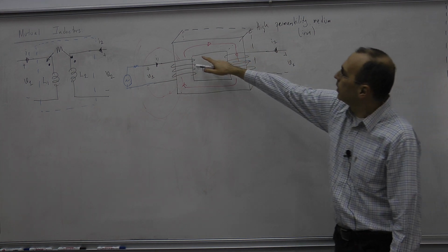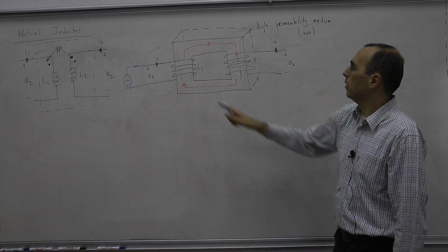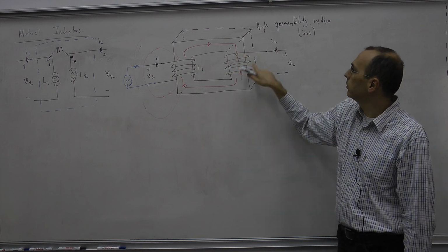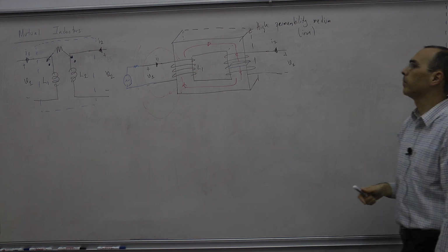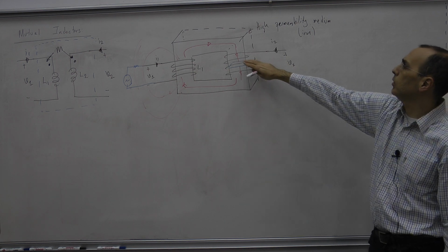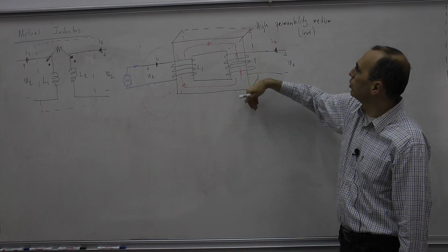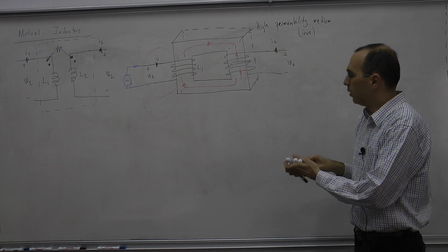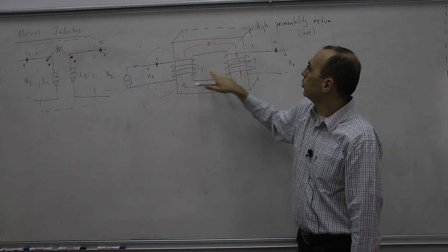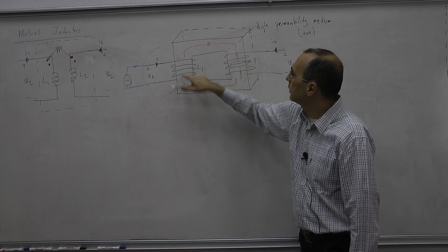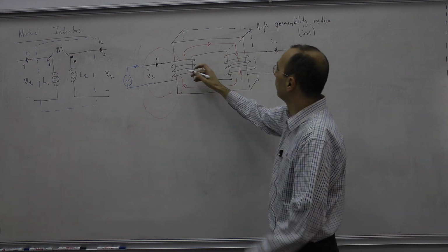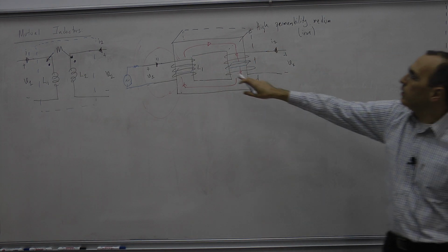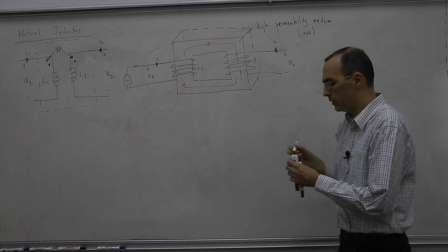Now, what is important is that this magnetic field produced by the primary coil, coil number one, is intercepted over this surface. This is the definition of flux essentially. As the B field passes through the surface, it introduces a scalar concept, flux. Similarly, the B field introduced by coil number one is also intercepted by itself over here. This is called the self-inductance. So the energizing coil is intercepting its own flux essentially.